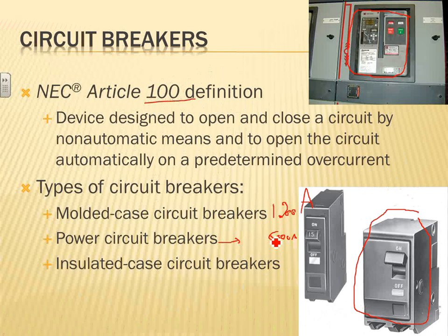Molded case circuit breakers, what they do is they mold them all together. You've seen them, it looks exactly like this one. And they can be electronic circuit breakers, or they can be thermomagnetic circuit breakers. It doesn't matter. Molded case is just how they build them. So when you go to the power circuit breakers, they build them completely different. It's a device that you can unplug, put on the table, and work on, as we all know.